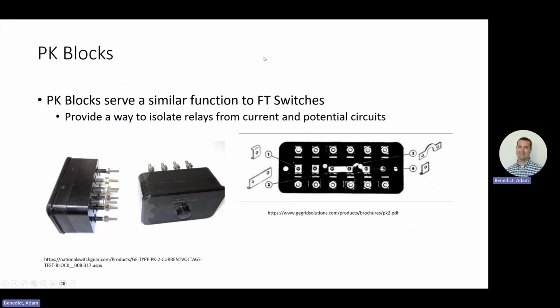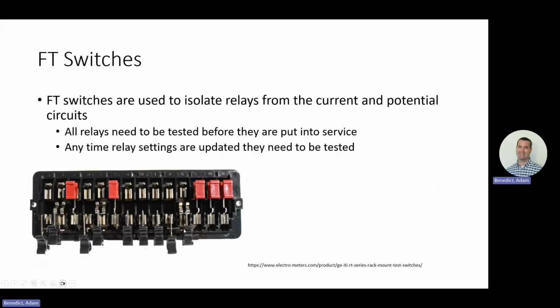So another isolation device is a PK block. The main difference is here you pull it down individually, which might not be ideal, especially with differential circuits. I guess high impedance differential in particular can be an issue, where you would isolate individual phases of the CT.